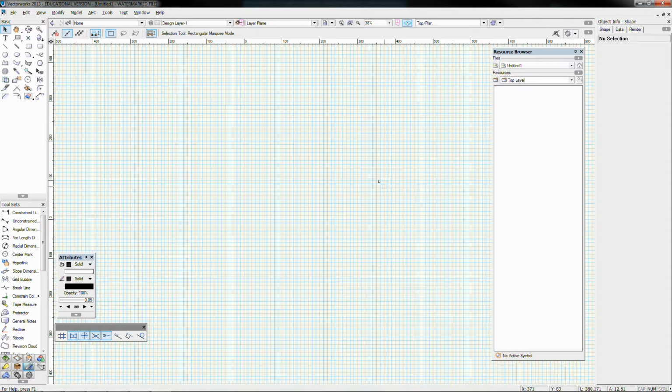Today we're going to be looking at importing, and when I say importing I mean specifically for plans. We're talking in the theatre world right now, and we're going to look at 3 different types of imports. This is also relevant to many of our other courses that we've been doing. I'm going to be looking at importing a DWG file, commonly brought in from AutoCAD, sometimes SketchUp as well, or you might just find it as a general venue plan. I'm going to import a PDF today and try and convert it out so we can use some of the snapping data from it. And I'm also going to import an image file and see what data we can get from it. So let's start off with the DWG file.